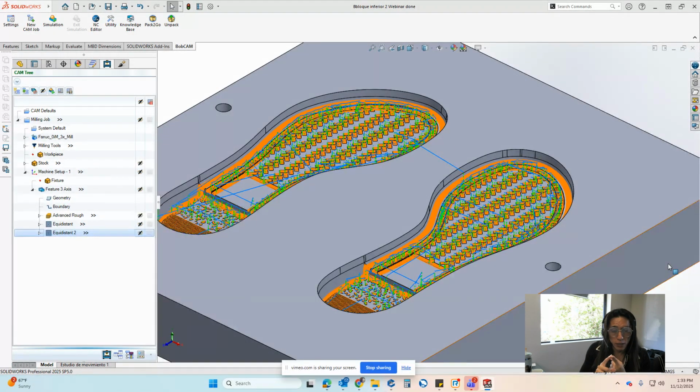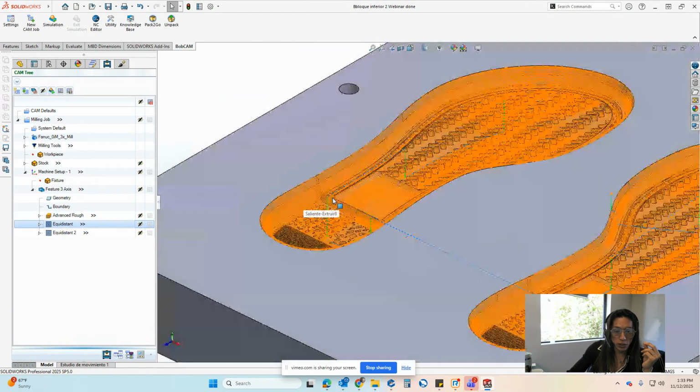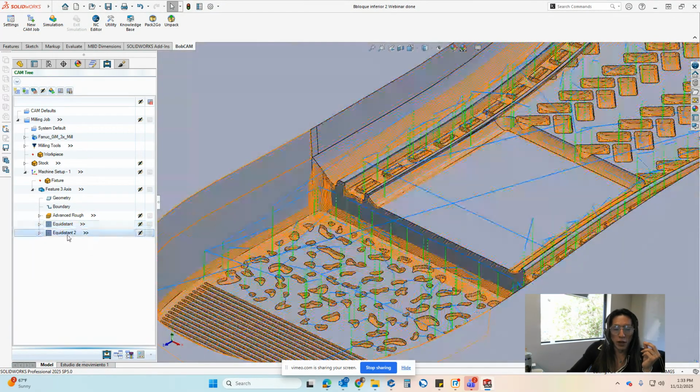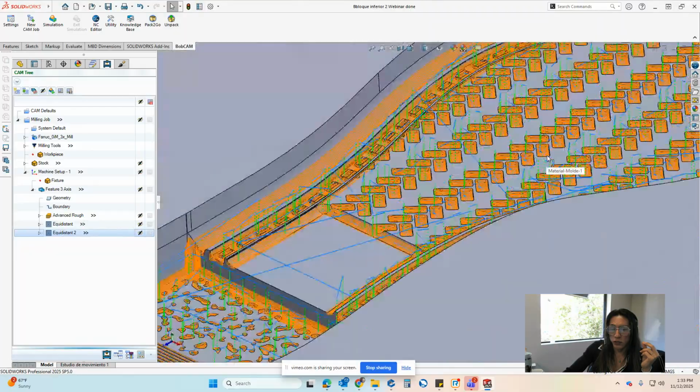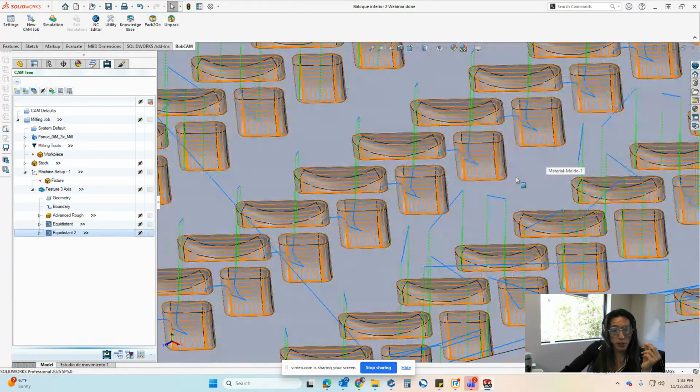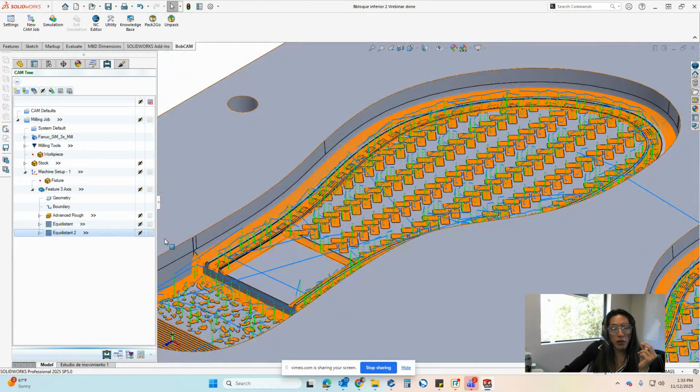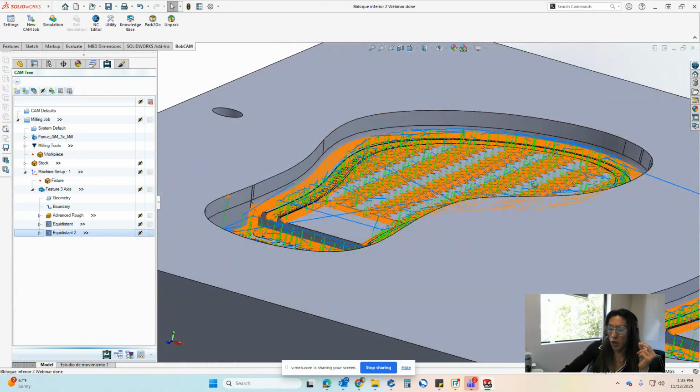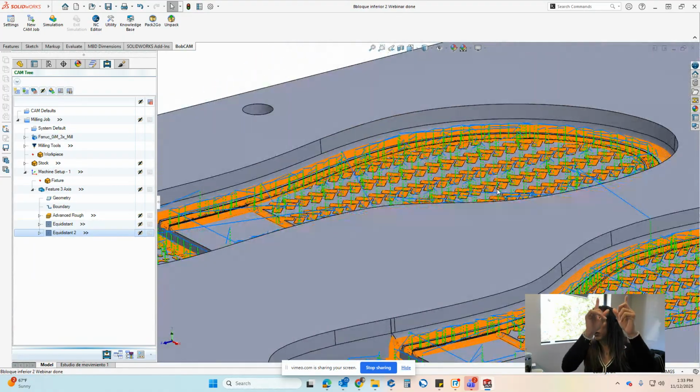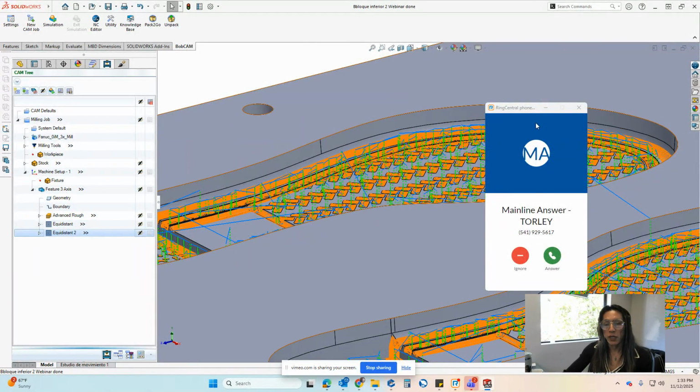Remember, we used the template, we modified the roughing operation, we used two equidistance offset, one equidistance to finish, like you see here, and then one equidistance to do rest finish on the areas that is necessary. Then we used the advanced interface to control the retractions of the toolpath so it didn't go all the way to clearance. Okay,